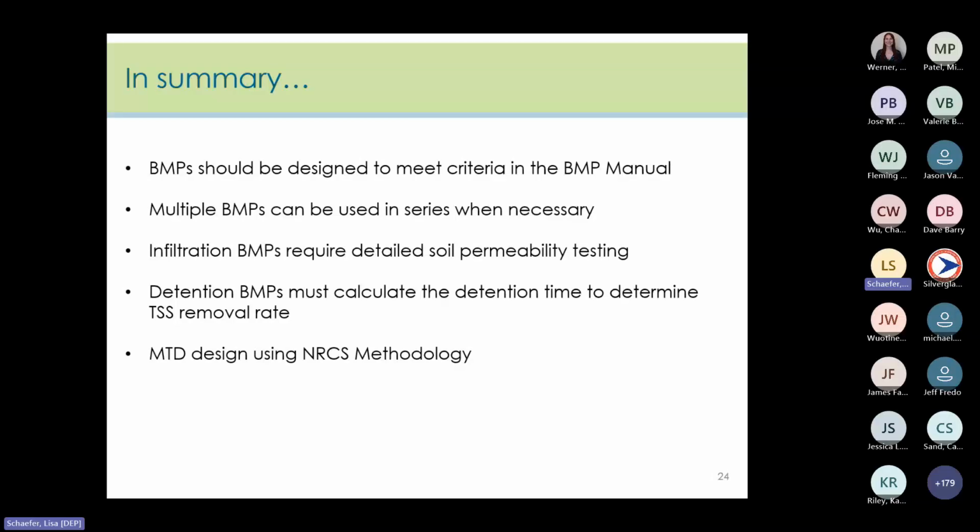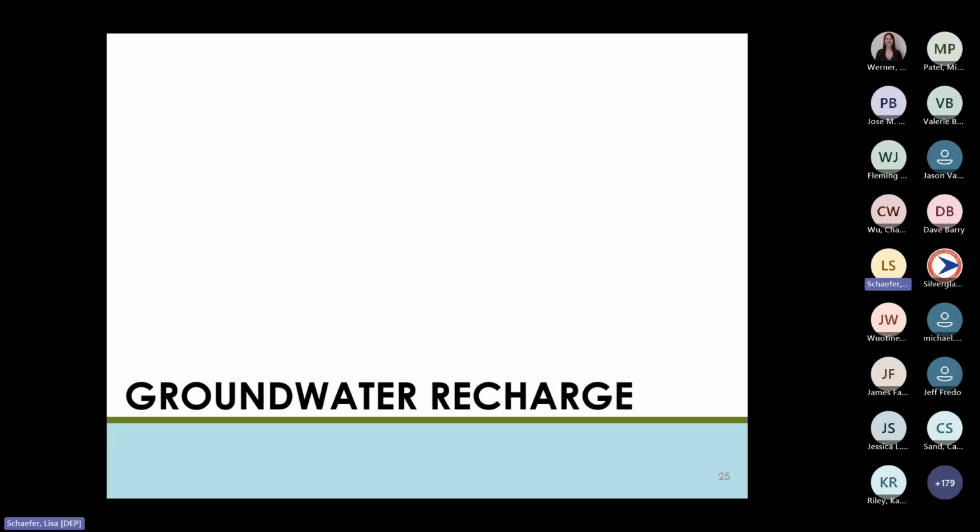All right, now, if you're in a situation where you need to swap out an MTD, you're revisiting a project, and you need to swap it out for a second one, please feel free to reach out to us if you're unsure about the sizing. We've had some instances, such as one where someone went from a filter type to a hydrodynamic one, and unfortunately, too small of a model was selected, and that resulted in water quality issues and flooding. So with that being said, it's time to go into groundwater recharge.